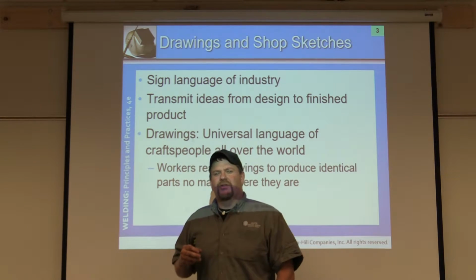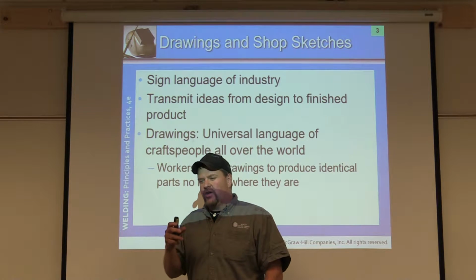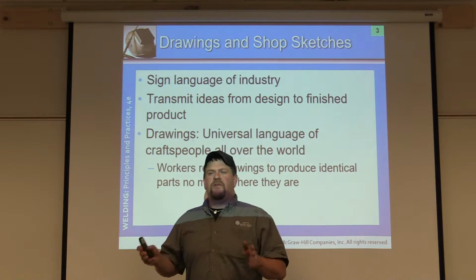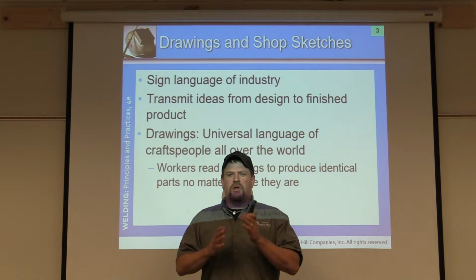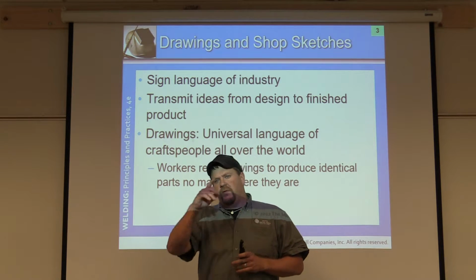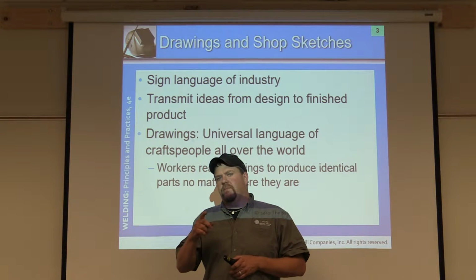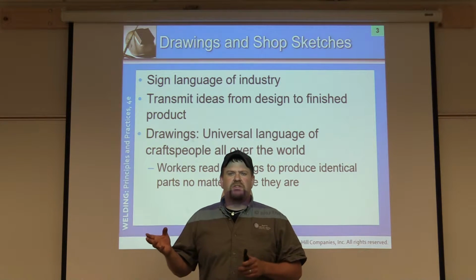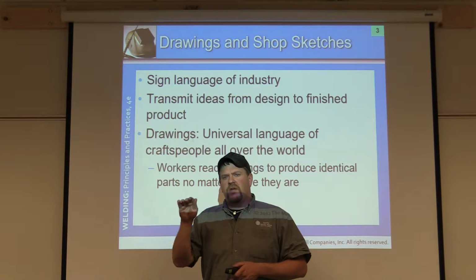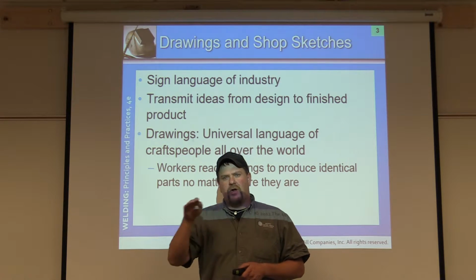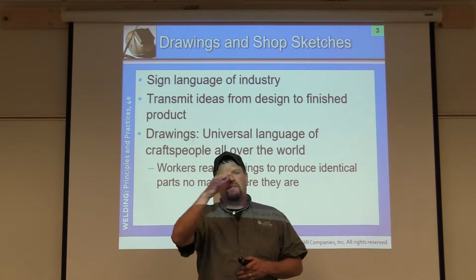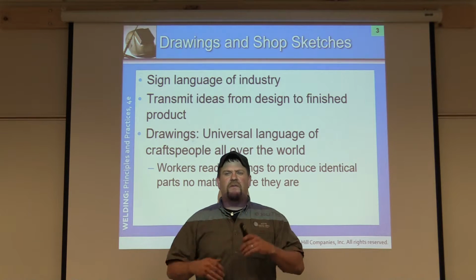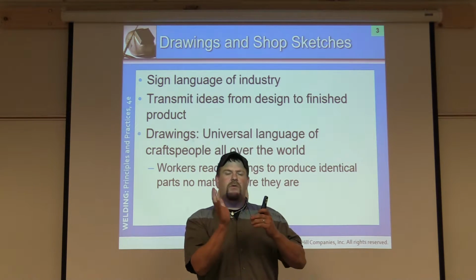And then there are times that you're not going to get the whole picture. You're going to be frustrated, there might be a part left out, or you may have to look at it and deduce several things from it in order to figure out the one portion. So for example, if we have a circle with a 3-hole bolt pattern laid out on an even spread, divided by 360, so we know they're 120 degrees off. We may try to find where it's at right angle, either 0 or 90, and that's our start point. And from there we'll have to make the calculations and do the mathematical formula to figure out, okay, what angle is this at, what angle is that at, relative to this.